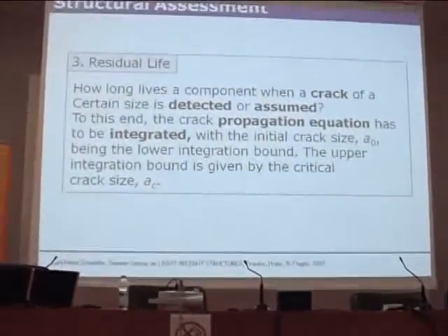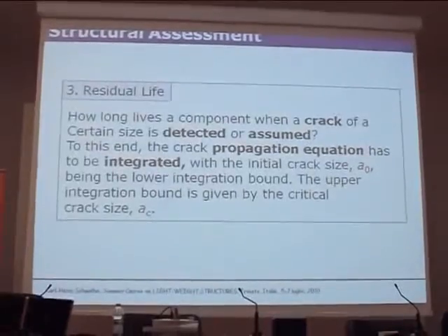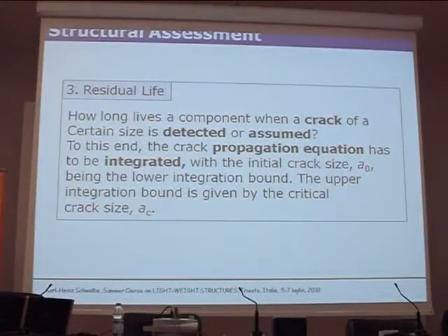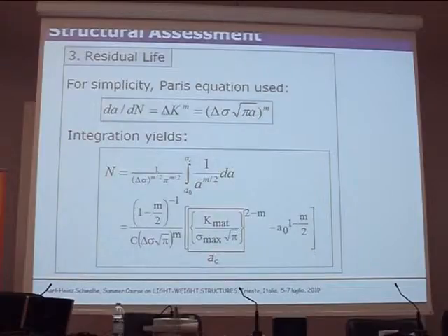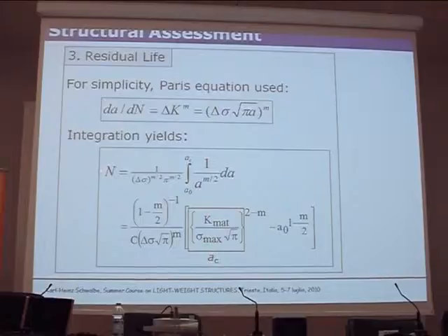Now, what I was just saying, on the blackboard here: what is the residual lifetime? We integrate the crack propagation equation, and we start from A naught as the lower integration bound, and the upper integration bound is given by the critical crack size. Then it becomes a bit more complicated. So I've done it for the Paris equation, very simple.